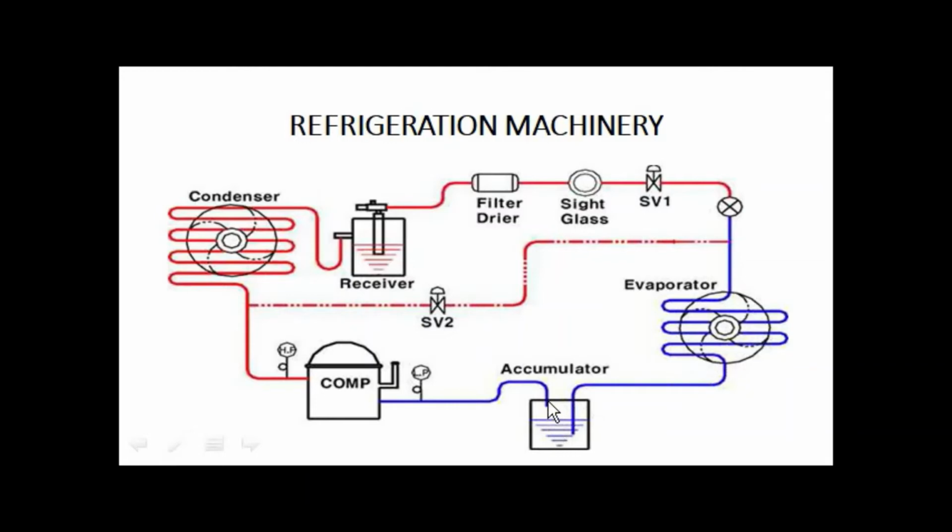The purpose of the accumulator is to separate liquid, or to prevent liquid refrigerant from entering the compressor, by separating liquid or any kind of moisture before entering the compressor.